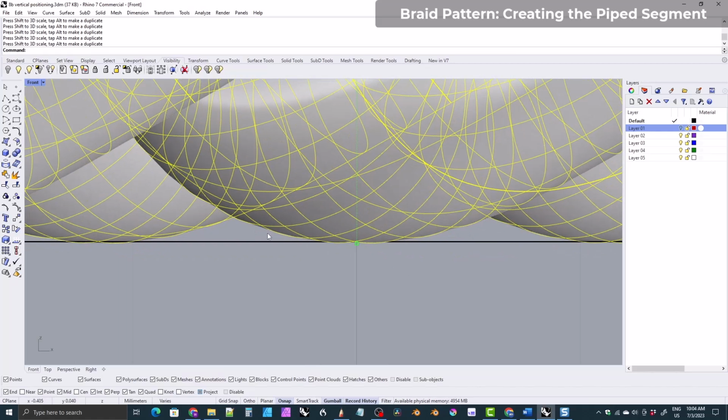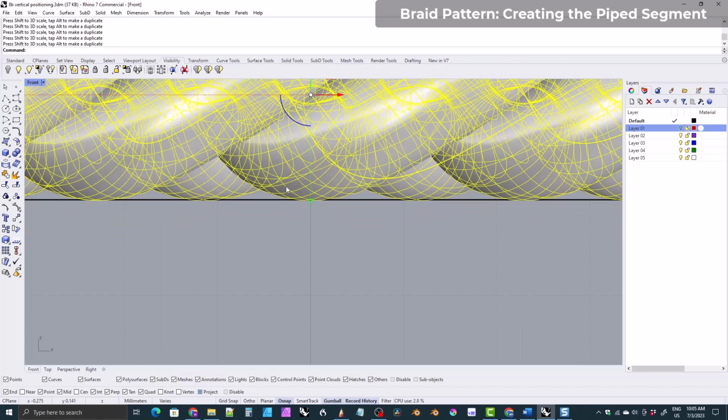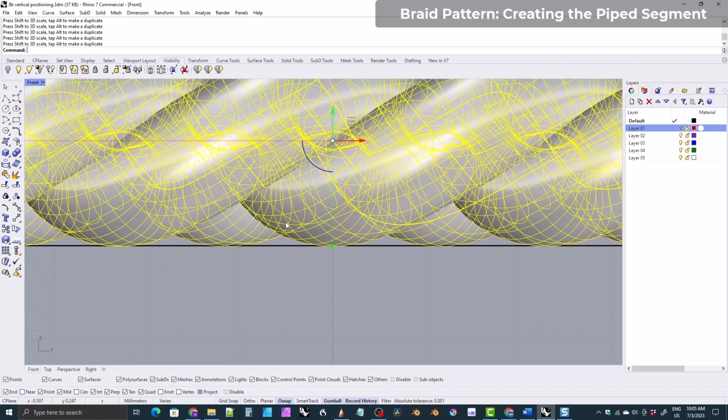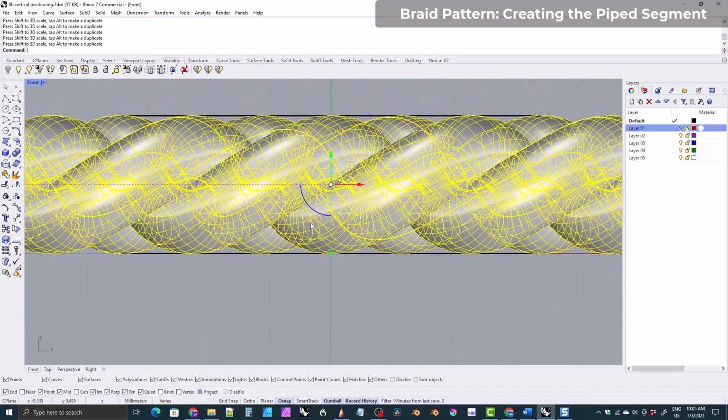Now, one problem you may run into: these notches here may cause the ring to act as though it is a larger ring size. So you may want to design this ring in maybe 3 different sizes. Maybe we're making this one a 7 1/4, so you could come down a quarter size, maybe do a 7, maybe do a 6 3/4. And then make those rings in resin, clean them really well to make sure there's no resin residue on them, and then let the customer try on the resin rings to see if they fit right.